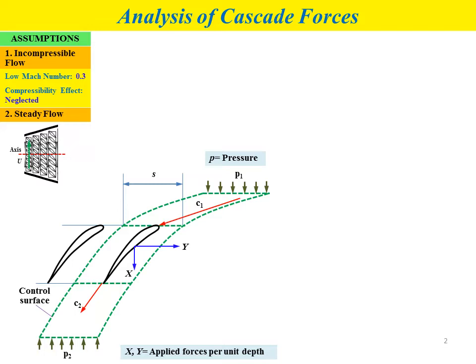The green arrow with parameter u, blade speed, represents the direction of the rotational movement, and also the value of the blade speed. We also have the inlet flow velocity vector. Let's say we consider the last rotor row of the turbine, and we also have C2, the outlet flow velocity vector.